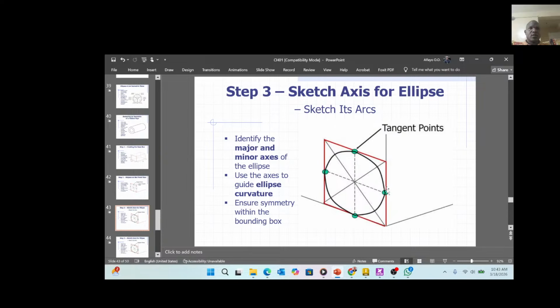And for the shorter diagonals, you place your pair of compass from the edge, start from this one, open your pair of compass to a span radius up to where the smaller arc was, and draw this longer arc. Also interchange your pair of compass to that point, and open to a span radius of these. You never even need to change the radius, because if you are accurate, it should be the same, and then do this arc.